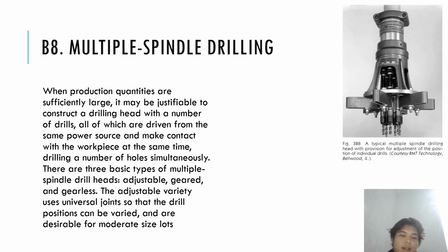There are three basic types of multiple spindle drills: adjustable, geared, and gearless. The adjustable variety uses universal joints so that the drill position can be varied, and is desirable for moderate sized loads. So this is the video.